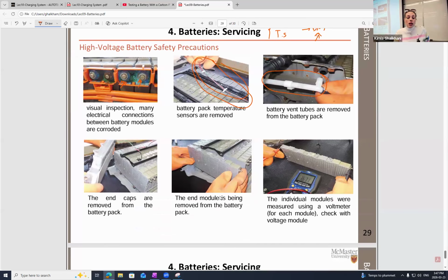And then we start from the end of the battery, removing the case, removing the first layer, removing the cap, and then taking out the battery modules. So for example, these are some modules connected, so we have to take them out. If you look here, I have one of them out, connecting the tabs. This is the positive and this is the negative tab to the multimeter. And I'm looking at the voltage of each module individually to understand.